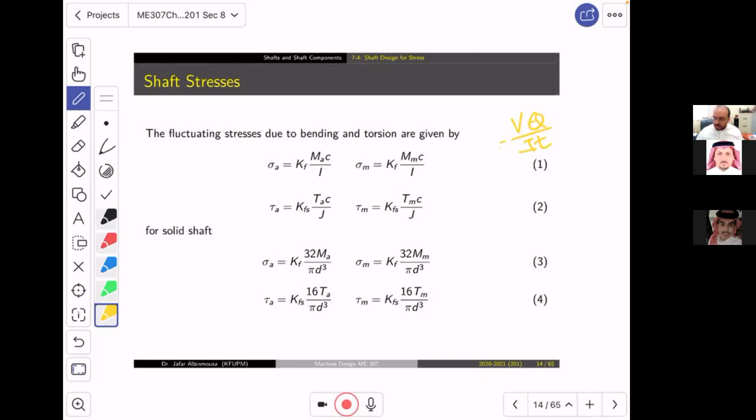You take this big gigantic diameter and apply a shear force of 10,000 Newton, you get a stress of maybe 5 megapascal. It is nothing. Same if you apply F over A over this gigantic steel cross section, what will you get? You'll get a normal stress of maybe 5-10 megapascal.